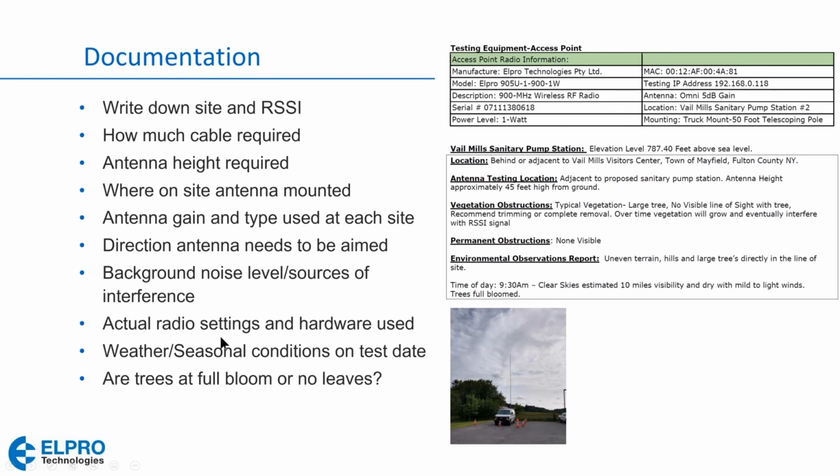For example, with the 915U2, we can get away with an RSSI of -90, and that gives us a suitable fade margin. But with the 945, that same radio has to have an RSSI of -70. So as long as we're using the same frequency during our site survey, we can substitute other radios for the final installation, as long as we know the difference in the sensitivity of those radios, and whether there is any difference in the transmit power as well.